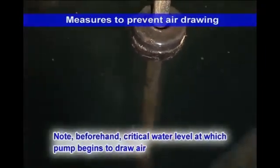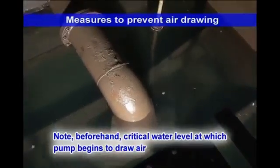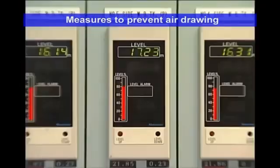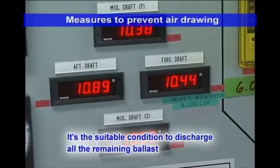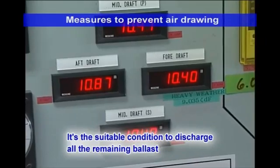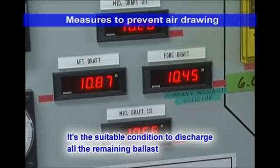Note beforehand the water level at which the pump begins to draw air, and stand on the alert as the water approaches the critical level. You may use other tanks with a suitable water level to continue discharging. With some ships, cargo planning is based on the hull with trim by the stern. It's the suitable condition to discharge all the remaining ballast.